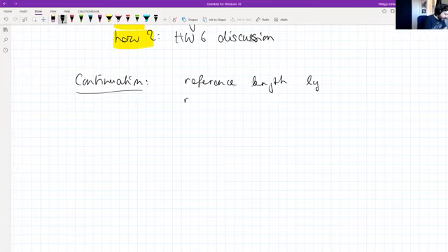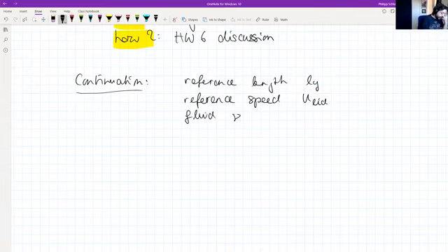We have introduced a reference speed or a reference velocity, which was the lid velocity. And we have characterized the fluid as usual with the viscosity. And this then allowed us in the first hand to define a Reynolds number, which was U lid times Ly divided by the fluid property, the viscosity.